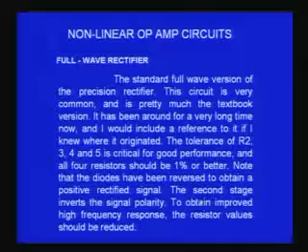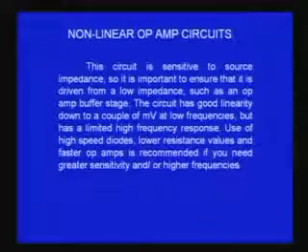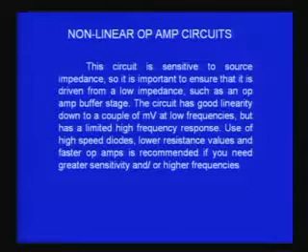We also have to worry about the high frequency response. The high frequency response of this circuit is not good when you use very large resistors. So if you want to improve the high frequency response, you have to reduce the resistors you make use of in the circuit, and you should also try to use a low impedance output from the signal source, the sinusoidal source.